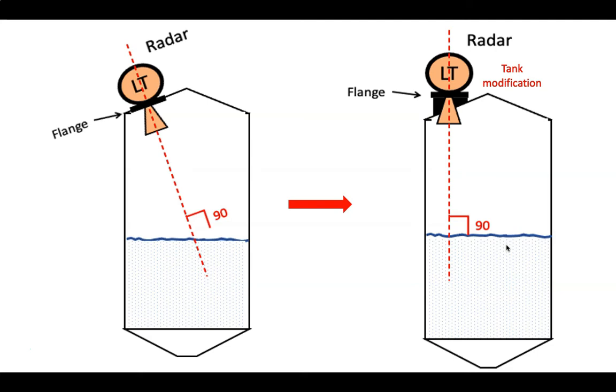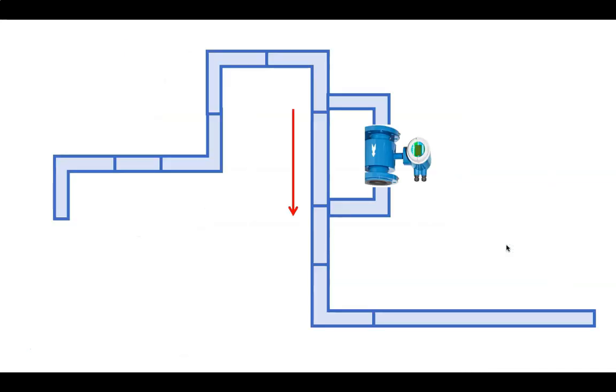about it. Also, if you understand the installation rules, you can work much better with the process engineers, because if a process engineer would say that, okay, we need to install a magnetic flow meter at this point in the plant, and you know that in that area there are too many pipe bends and other pipe elements that will affect the accuracy of the magnetic flow meter, then you can say that no, installing the meter in that area is not a good idea. So then they can find another place where they can measure the flow rate of the liquid in the pipe.